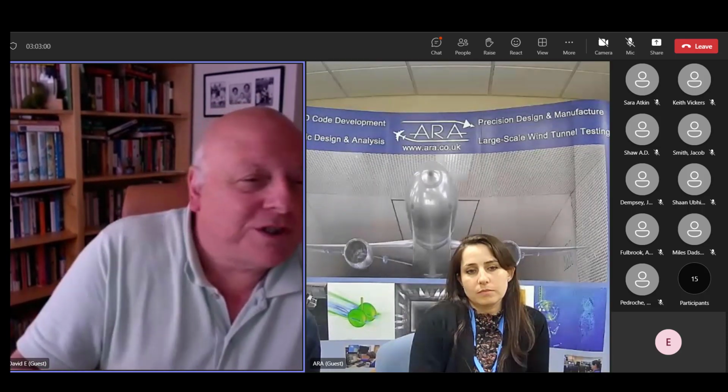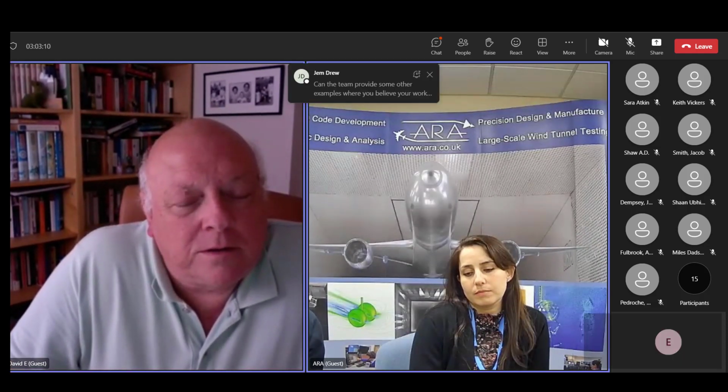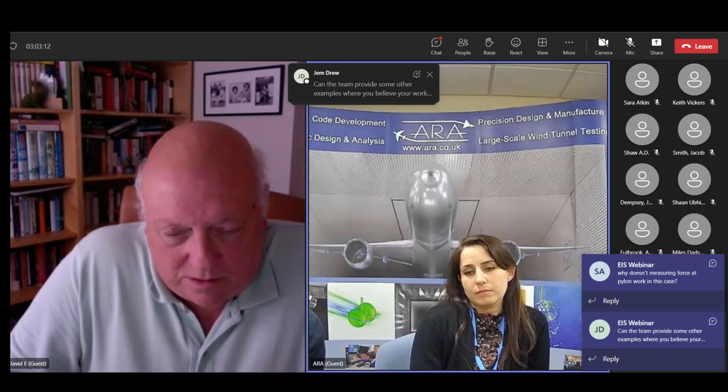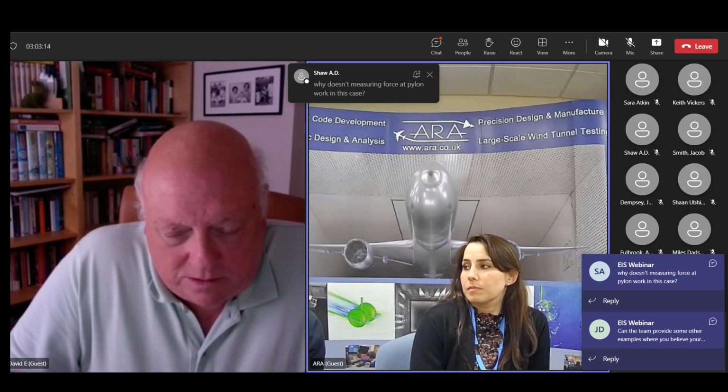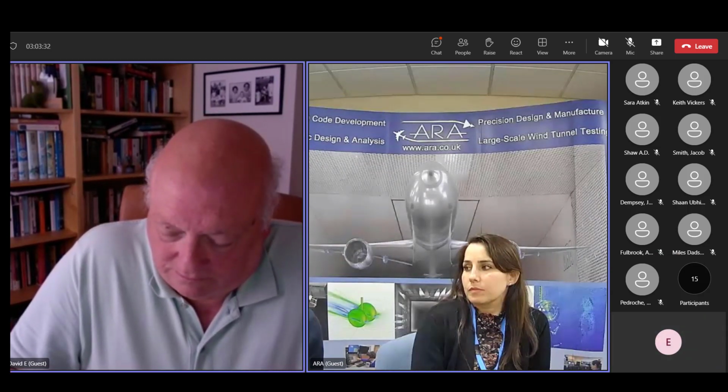If you're talking about, that's the effect on, say, an axial load if you put a side load on. Oh yes, well, this all comes from the calibration. This is allowed for within the calibration. So what we do is we apply calibration loads in axial force. At the same time, we apply varying normal force loads, and we use a multi-optimization tool to provide a mathematical model of all the balance outputs depending on all the inputs that are all varying at the same time.